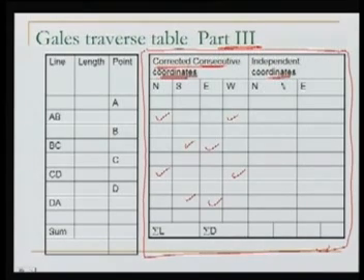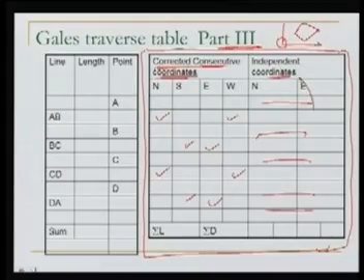The only thing is, what generally is done, we try to take our entire traverse in the first quadrant. So you can select the origin accordingly, and then you have these coordinates for all these points. Once you have the final corrected independent coordinates, there is no closing error and you can use these coordinates in your work.